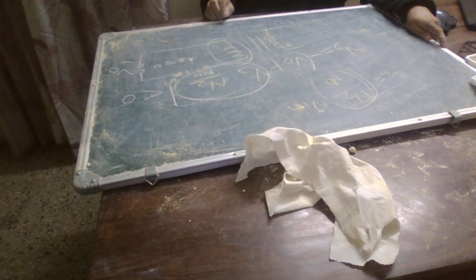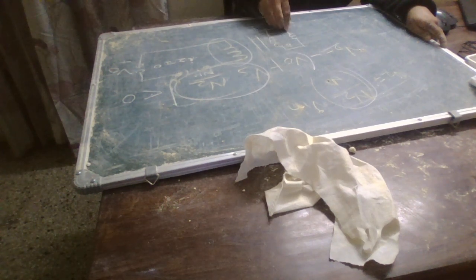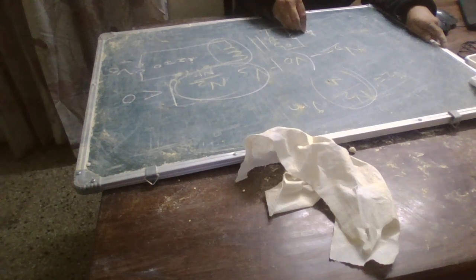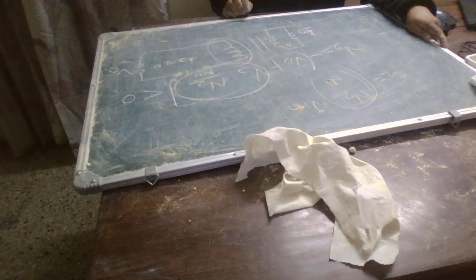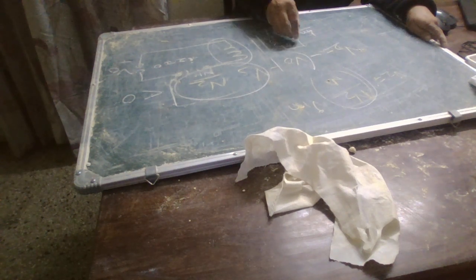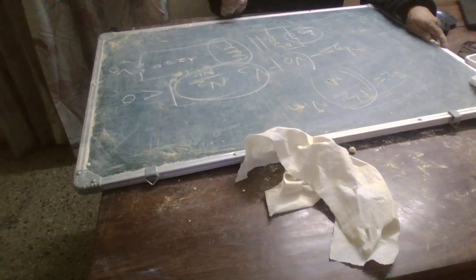So when the switch is closed, current is increasing linearly in the magnetizing inductance. The current is going to increase in this magnetizing inductance, and there is no current in the windings of the ideal transformer in the model. That's why this LM parameter is very important, and we have to avoid saturation of this transformer.